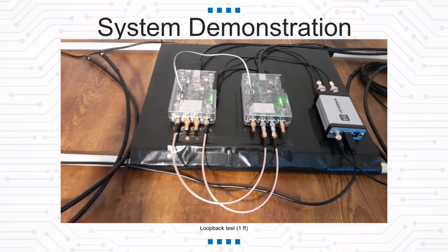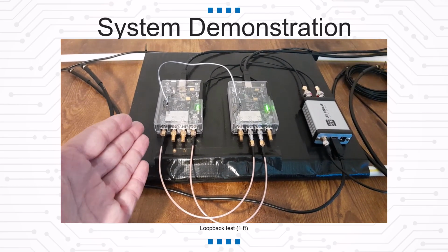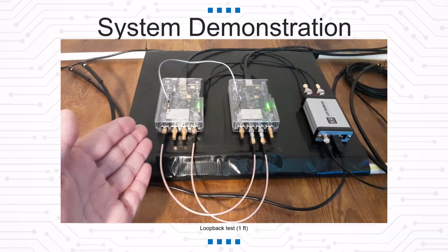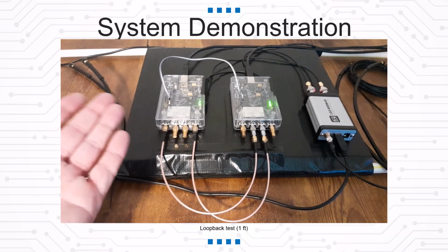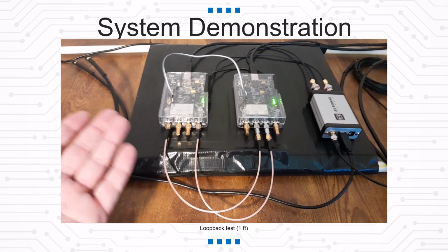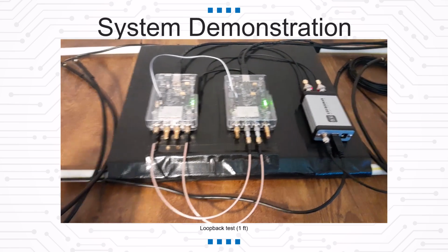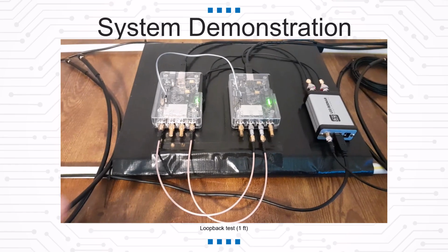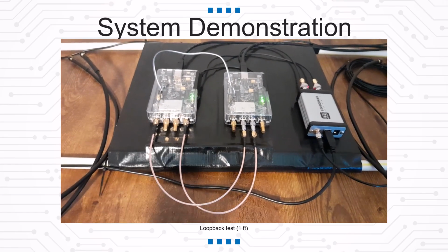If we were not using the GPS disciplined oscillator, in software I might tell the master module to read 2.4 gigahertz, and that could be off. And then I could also say 2.4 gigahertz for this one, and that will be off, which will give us a lot of errors. So it helps just keep them both synchronized.